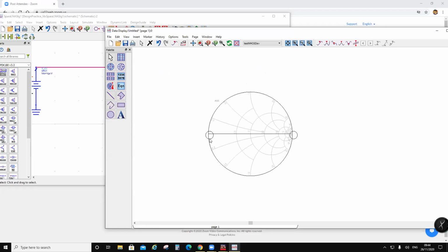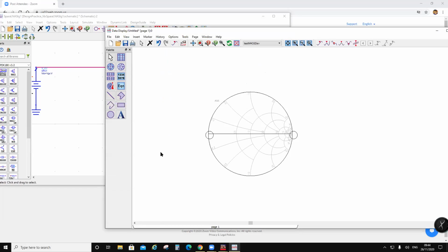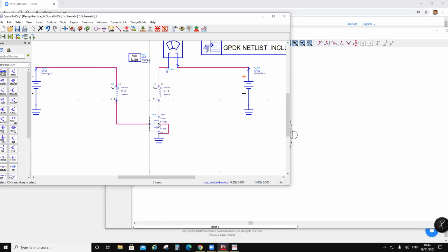This is something I try to tell many people, but they don't believe me. They just put the supply here and here, sweep them, and plot the output and transfer characteristics. But when the transistor becomes big, it tends to become unstable. When it oscillates, the DC current drawn is going to be much higher, so your DC curves are going to be wrong.